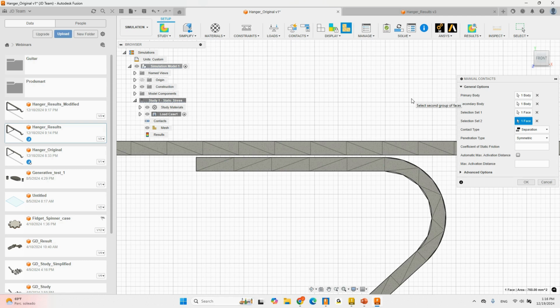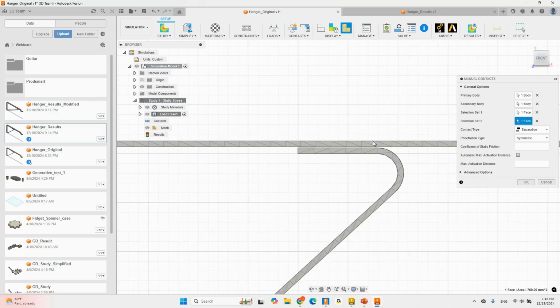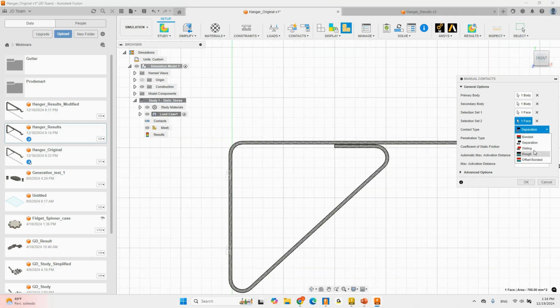So in order to do that, it's not just going to calculate one solution, but it needs to run several solutions. It's an iterative process, right? It's going to calculate first for little loads, then another one, another one, another one. Like you're analyzing it through time, right? I'm analyzing at moment 0, 0.1, 0.2 seconds, 0.3, and so on, okay? So the more complex the type of contact is, the longer the simulation will take, and the more expertise you need to know about the contact solution, right? But you get all those options right there.